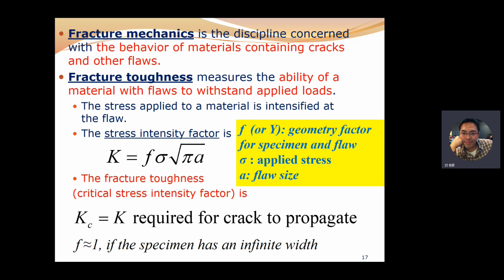What's the ability of the materials with flaw to withstand applied loads? Therefore, for the fracture toughness, the material is not perfect, it's not ideal, right? Therefore, we provide a factor called the stress intensity factor to define the fracture toughness.